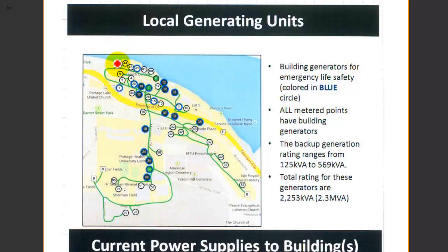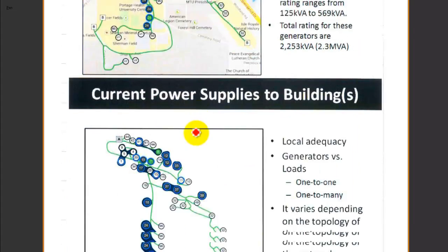So we have backup at the substation level. We also have the backup for each building, and then we also have a redundancy between two feeders. One is a primary, one is a backup, and that backup we usually refer to as a tie switch or normally open switch. So we have three redundancies in the Michigan Tech system, not to mention that we have an underground system. So we probably have one of the most reliable systems in the UP.